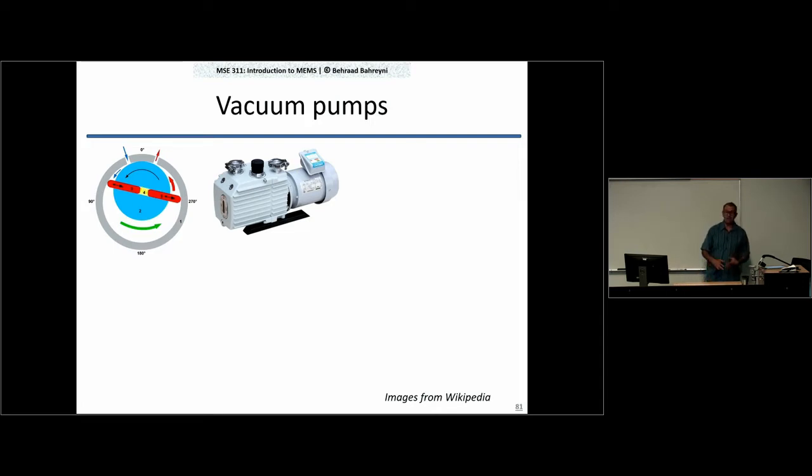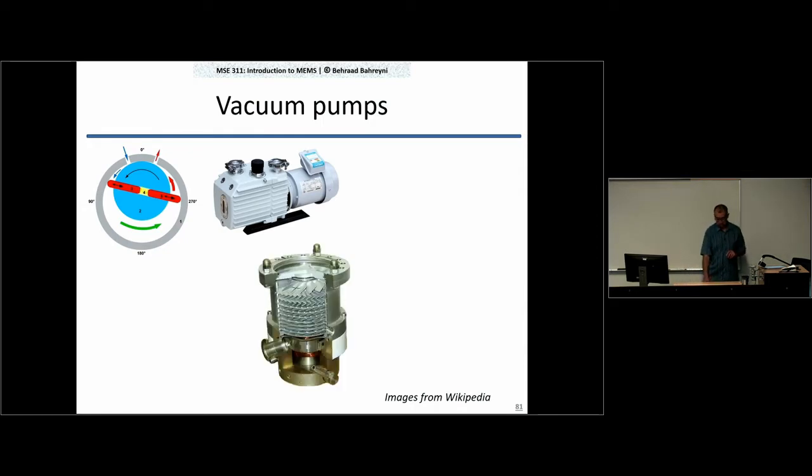They're called mechanical pumps, roughing pumps. And this is one method of operation for these mechanical pumps. There are many different types, but this is probably a bit easier to understand. These roughing pumps can go from atmospheric pressure levels down to about 10 millitorr, maybe if you push it to about 1 millitorr levels. In most cases, you need to go below those ranges.